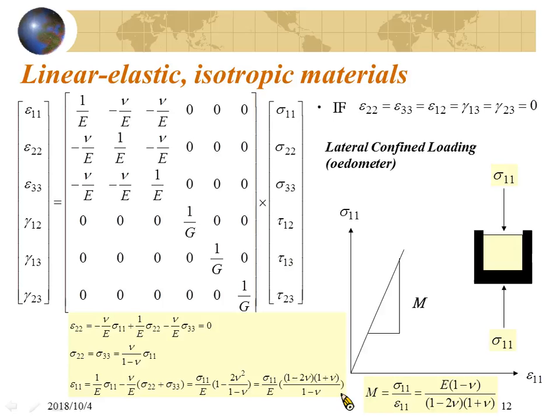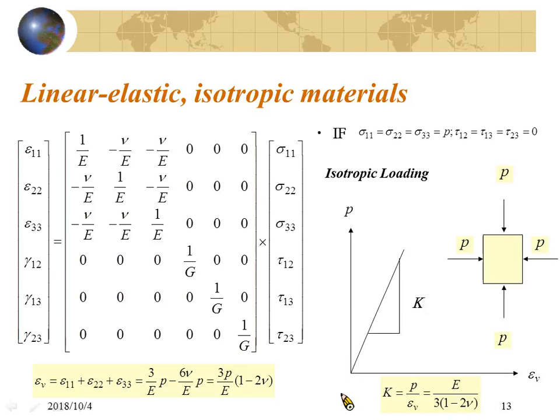Anyway, I want to tell you, you will have several different kinds of elastic constants, like the constraint modulus. But the constraint modulus can also be expressed as a function of Young's modulus and Poisson ratio. So how many elastic constants do you have? Only two independent elastic constants. I will introduce another important elastic constant. We call it bulk modulus. You have always heard about bulk modulus.